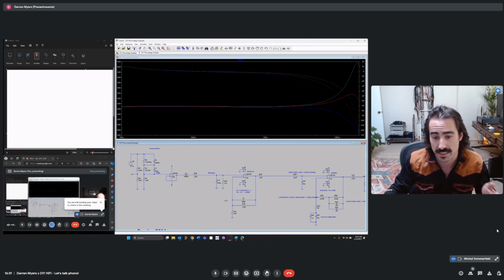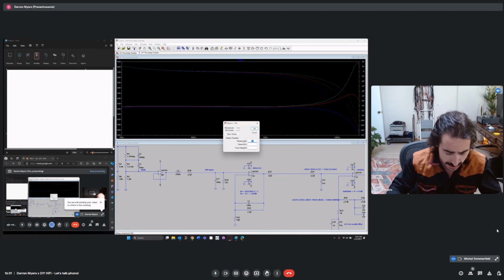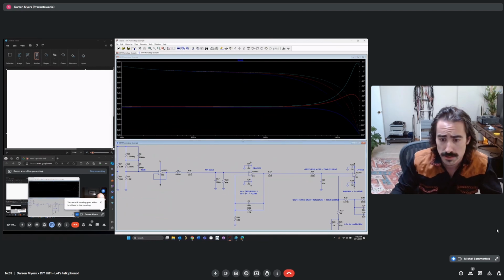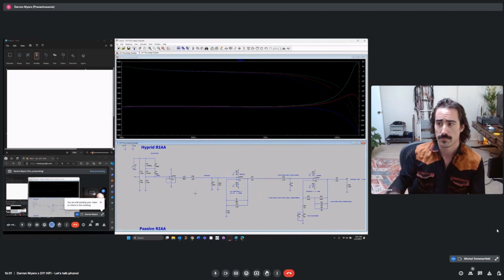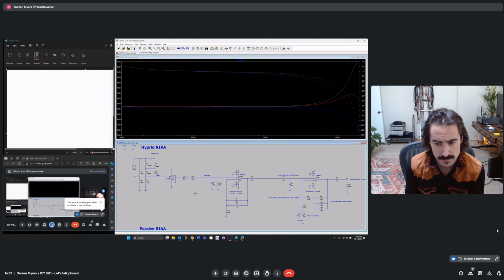And that's why it's nice to know the capacitance per foot of that cable that you use, so that you can calculate it into the overall loading that you're going to have. So if we would have some sort of a short takeaway from this part, how would you say was the best way to tune the input circuit?